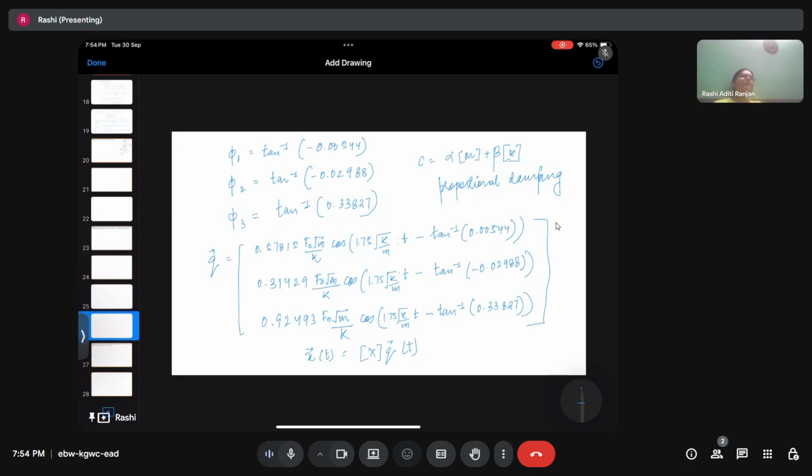So when we are talking about a practical problem, what is even the need of modal frequencies? First thing, never oscillate the system at the modal frequencies because at that time it can show resonance condition, right? We should avoid it. Second, that is what modal analysis is needed for. Second thing is that when we are talking about the system, like the structural system, wherein the mass and stiffness is very, very high as compared to the damping value.